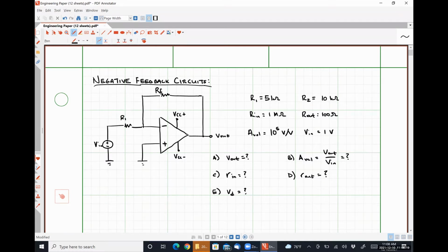This closed loop gain also depends on linearity because we need it to not be operating in a saturation region, where some change in the input voltage actually causes a change in the output voltage, which is not something that we've experienced with the previous circuits. So these are three new parameters that we're only really going to have to deal with for a negative feedback op amp circuit, because negative feedback op amp circuits are intended to work as an amplifier, linear amplification. You put 1 volt in, you get a scaled version of that 1 volt output.